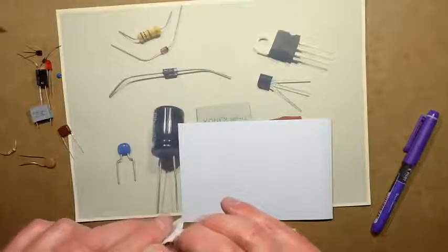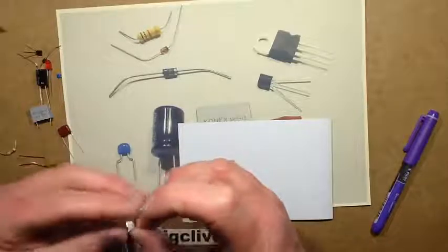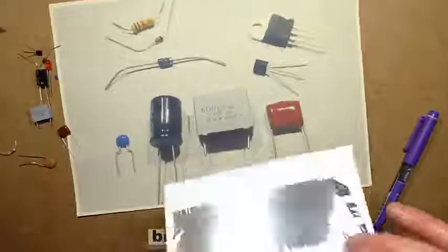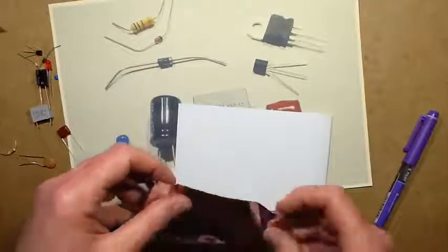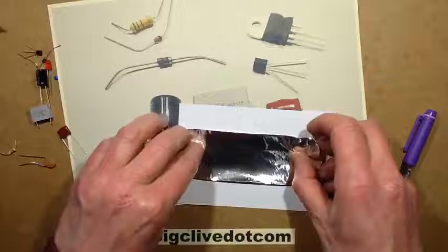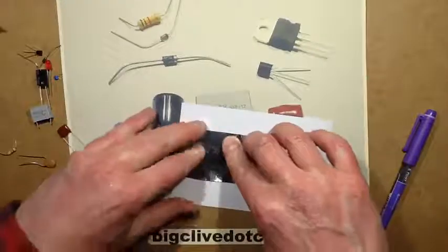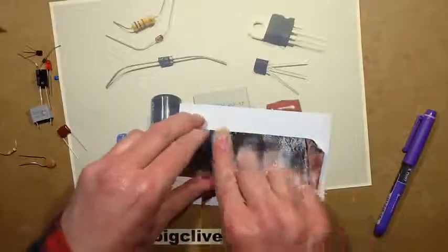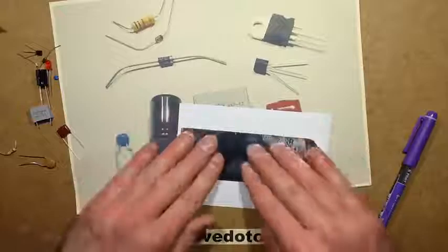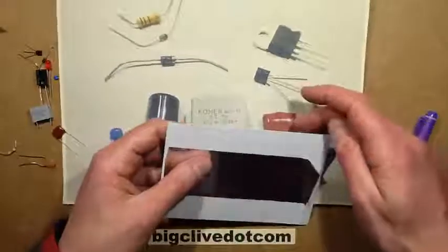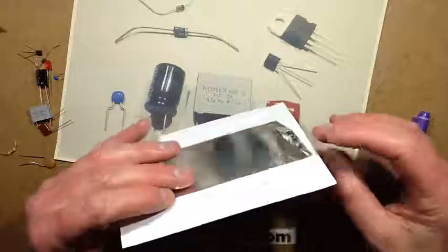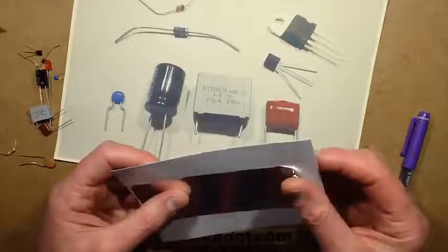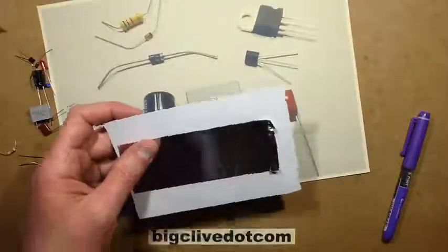And this is the physical construction that's used throughout all capacitors. They're all pretty much like this, but not using cardboard and aluminium foil. So let's get that as close to aligned with the other one as possible. And the 2 factors determining the capacitance here are the area of metallization that's in parallel with the other one, and how thick the insulator is in between. And you'd think, this card is very thin, so it's going to be a modestly high value of capacitance, but that's not true. This is not going to be a high value of capacitance at all.